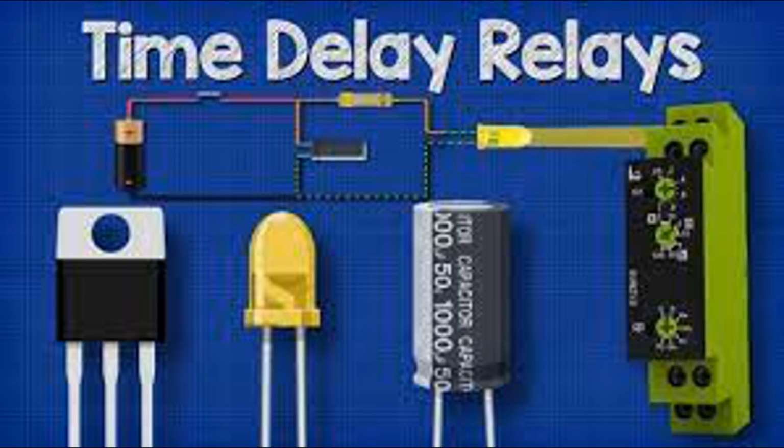Switching mechanism. The movement of the armature due to the interaction with the magnetic field triggers the switching mechanism of the relay. In a typical relay, the armature is mechanically linked to the relay's switch contacts. When the armature moves, it either opens or closes the switch contacts, thereby controlling the flow of current in the relay's output circuit.